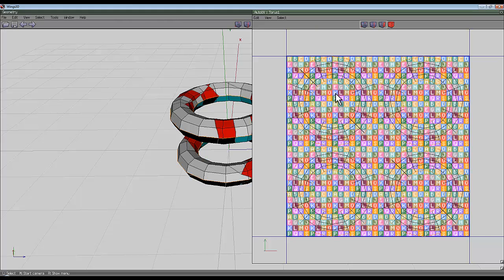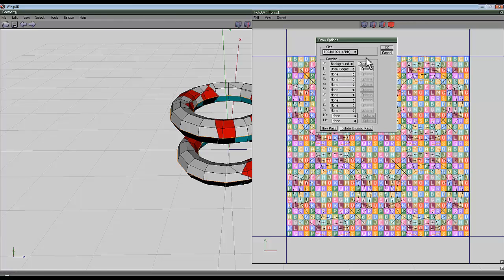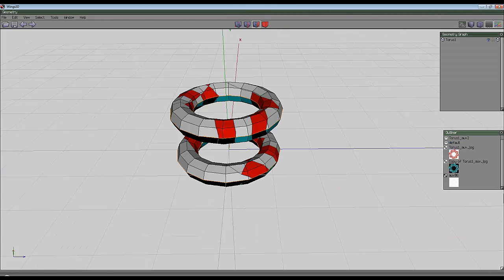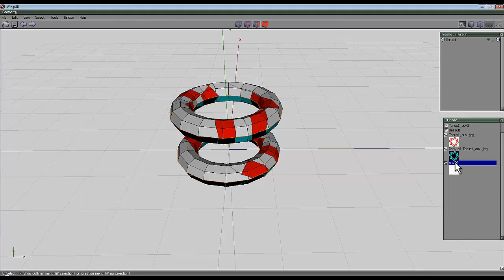And now I want a template that's going to be for these, so I right click, create texture, and just check that I'm on color white and go OK, and then close that. So this has created another texture here, so I'll just rename this one together. Bearing in mind we've done the UV map and it's associated with the geometry, not the textures,